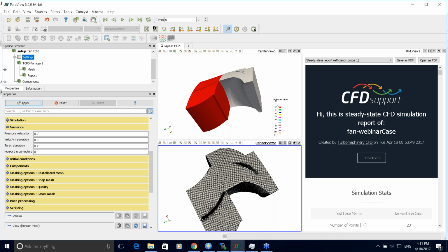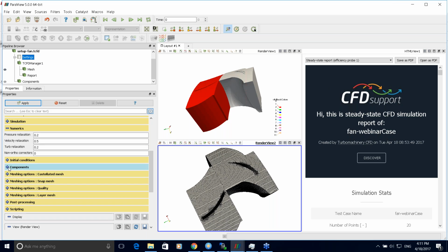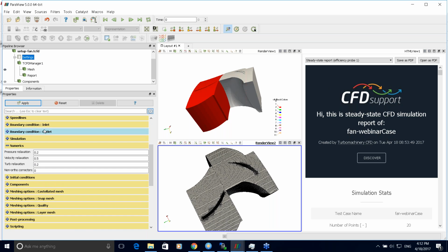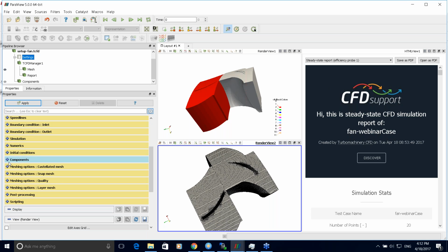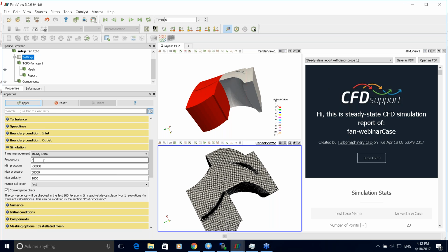Okay, well, it depends on a lot of parameters. In general, you can set any number, but it depends on your hardware. If you have just 100 cores, there is no way why you should set 200 cores. You can, but it slows the computation. So there is no reason to do that.